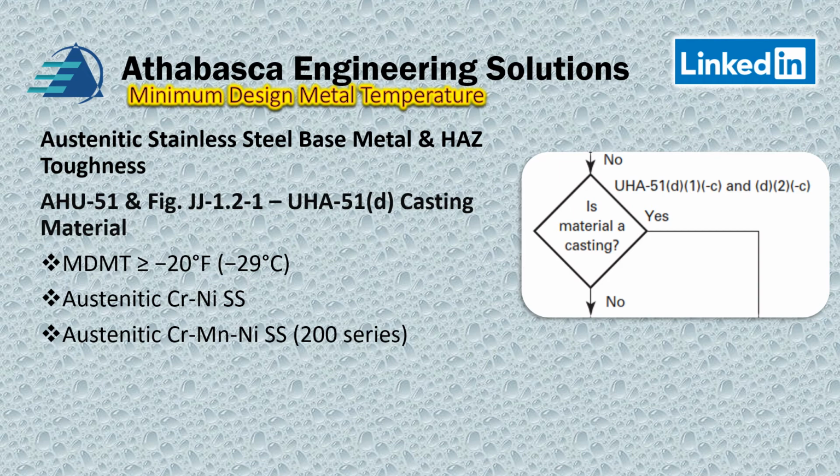So it's a very, very general thing, because I go through all the steps. If you're not really using it at cold temperatures, maybe you're using the stainless steel for corrosion protection, not for cryogenic reasons. And so that rule applies to your chromium nickel stainless steel, your Series 300 and your Series 200. And Series 200 has the manganese in the product.